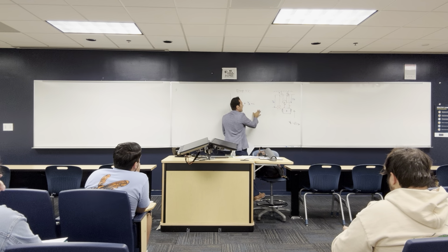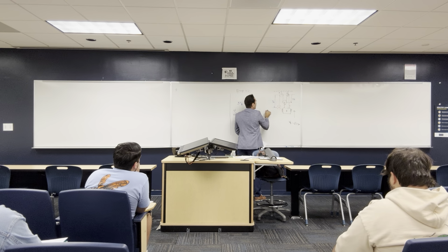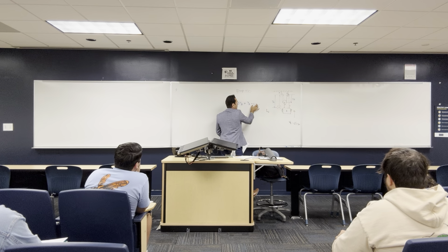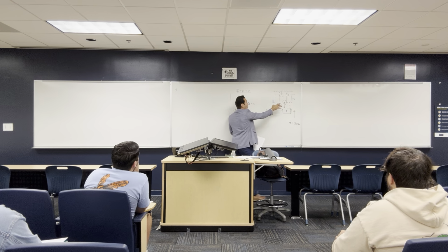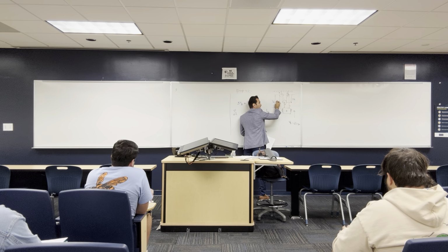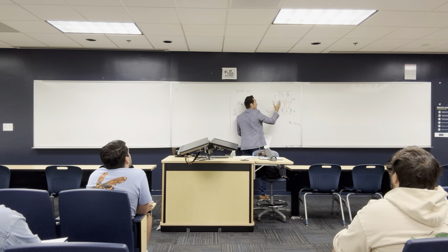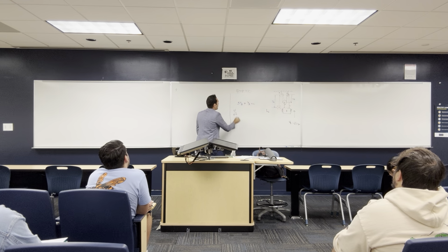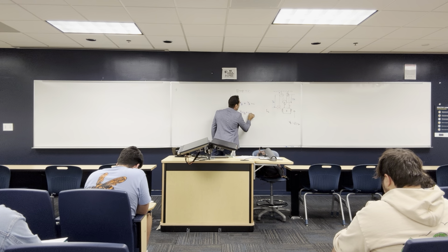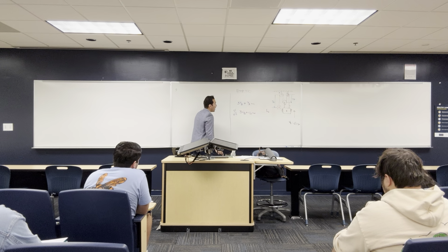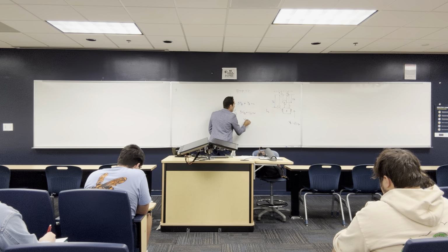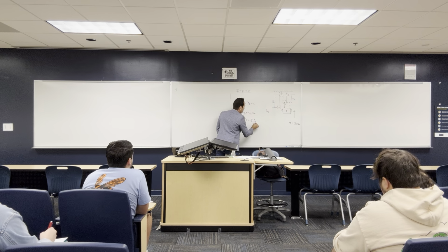So rather than saying all these lengths are equal to the length of the cord, I'm saying that the two variable lengths are always equal to constant, because if this decreases, it's gonna give more length to this. So this plus this is gonna be equal to constant. All right, so I have here 3 VB plus VA is gonna be equal to 0. I already know what is the value of VB, so VA is gonna be equal to negative 3 VB.